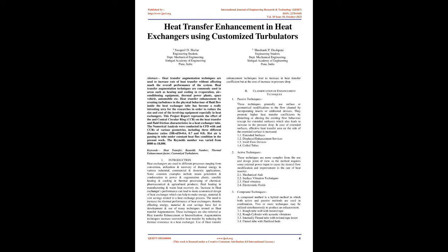The need to increase the thermal performance of heat exchangers, thereby affecting energy, material and cost savings, has led to development and use of many techniques termed as heat transfer augmentation. These techniques are also referred to as heat transfer enhancement or intensification. Augmentation techniques increase convective heat transfer by reducing the thermal resistance in a heat exchanger. Use of heat transfer enhancement techniques leads to an increase in heat transfer coefficient but at the cost of increase in pressure drop.